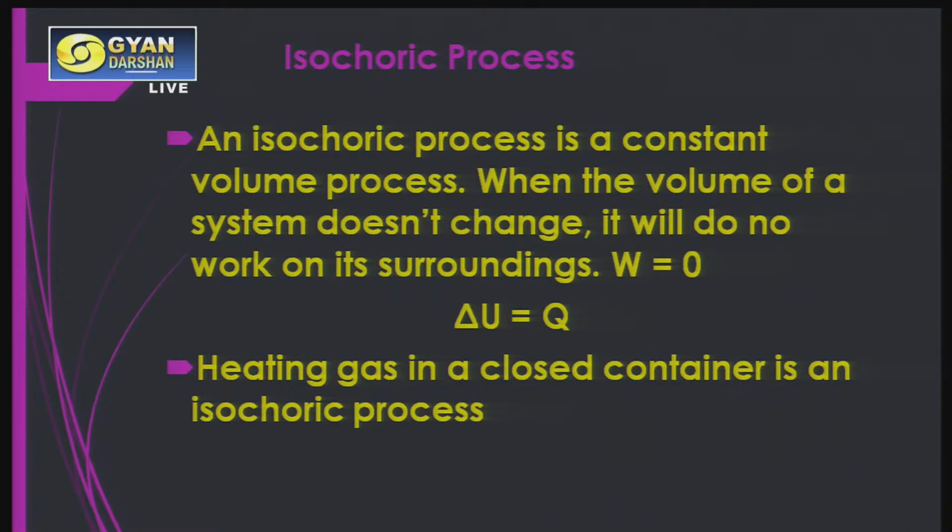So we can say that it is heating in a closed container. Whenever we are heating anything in a closed container, it is always an isochoric process. And here, when the volume of a system doesn't change, it will not do any work on its surroundings. So W is 0 here, and the internal energy change will be equal to the heat transfer that is taking place in this particular process.